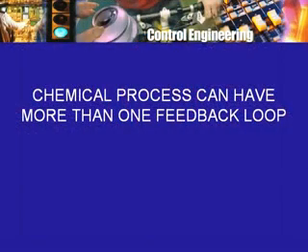We had talked about this feedback loop, and I had said that in chemical process situations where there are a large number of variables which are to be controlled, there are a large number of feedback signals, and therefore there is more than one loop. So if you draw the signal flow graph for a chemical process example, not a very simple but maybe even a practical one, you will end up getting quite a number of loops. So the rule has to be complicated because it has to take care of such complex situations.